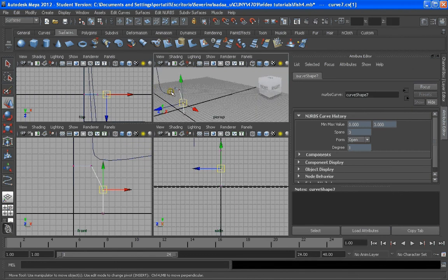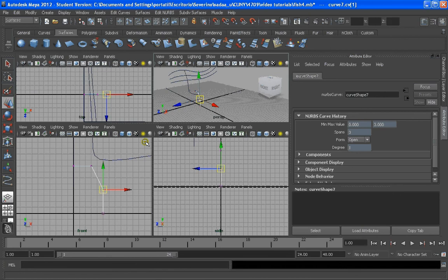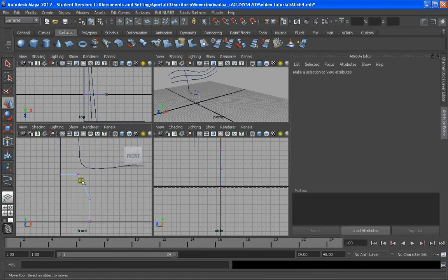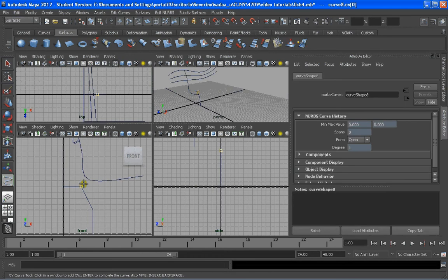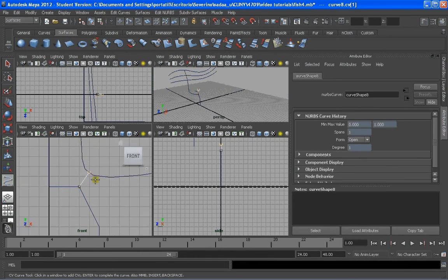from that curve that we're gonna put it together afterwards. So some of the lines that we're going to do, we're not going to snap to this curve at all. We're going to maintain them flat. So I'm going to create another curve, which is going to remember that it's a polyline, and by pressing Z, I'm snapping to the curves, and also remembers this corner thing. So we can start there and finish here and press Enter.